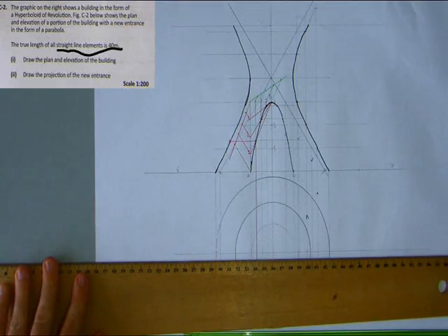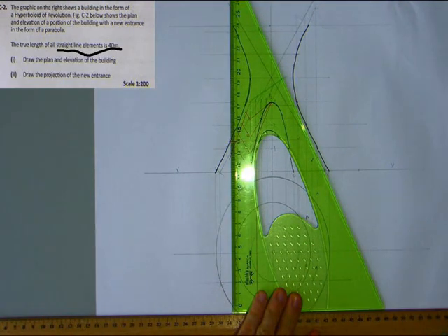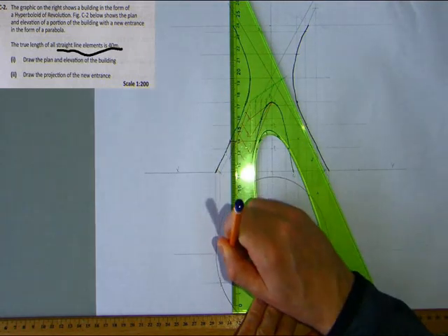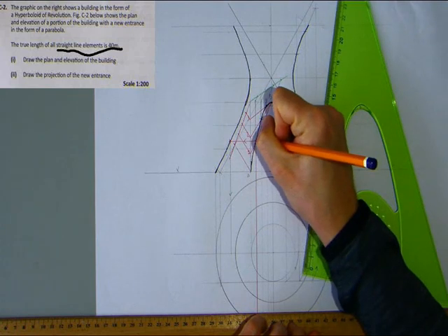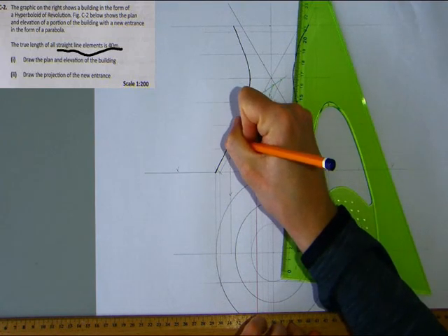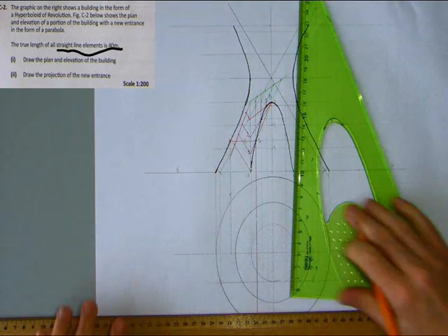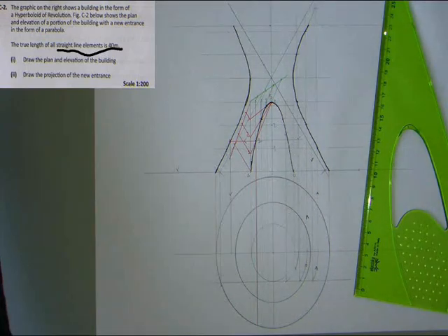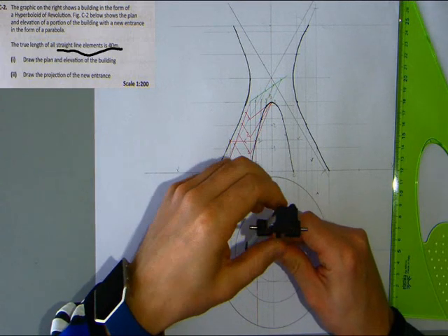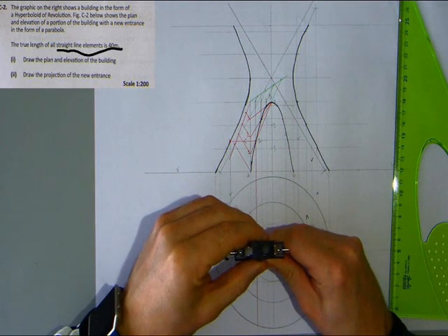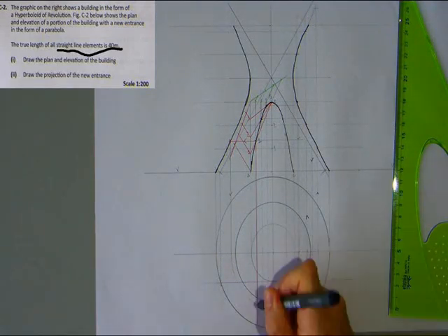Okay. And if I bring that down to the extreme generator, which is a horizontal cut essentially, so I'm taking this point 1 out to the extreme generator. Where is that in our plan view? Well, it's on this line down here. And if I swing that around now to hit my red line, we'll have a known location. So we swing that around and there's our location there.